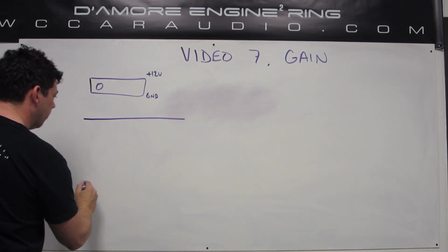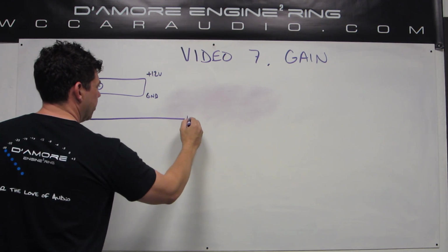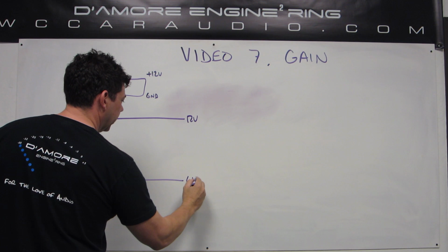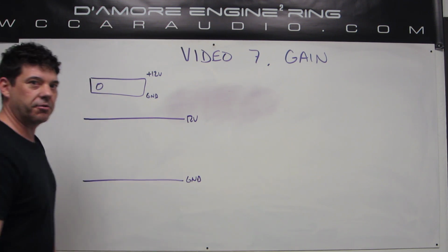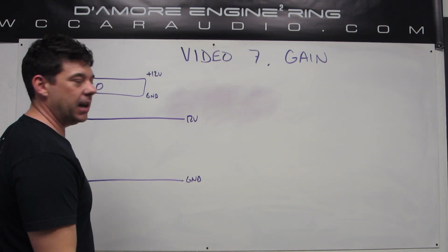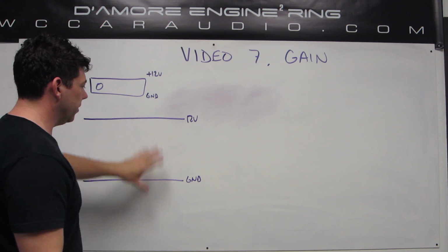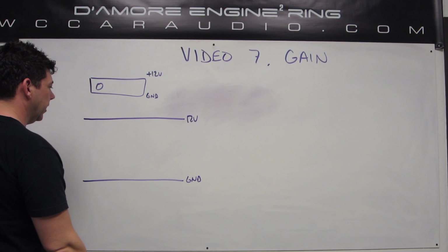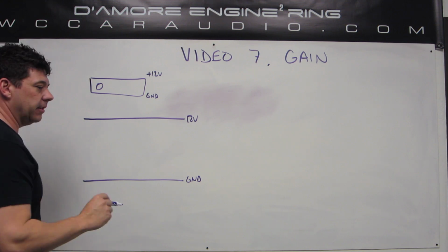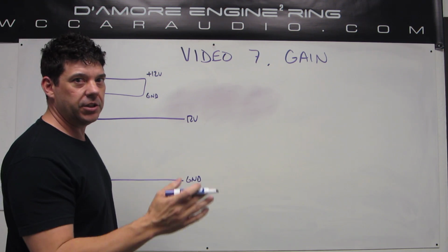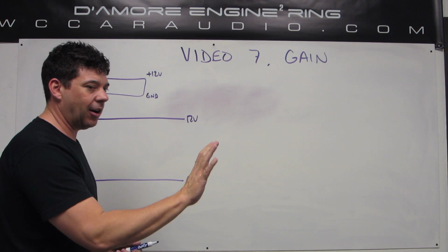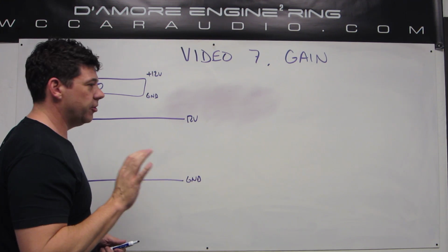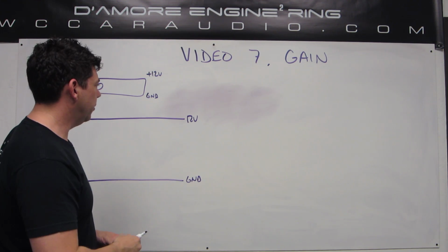So when you draw them, if I say this is 12 volts and this is ground, it looks like rails, like for a train or something. So it's kind of where the name came from. So the rails in the head unit are 12 volts and ground, and we're trying to fit our audio signal in here. Well, audio signals go positive voltage and negative voltage. That's why a speaker moves out and then back in. To generate a sound wave, you need to do both.